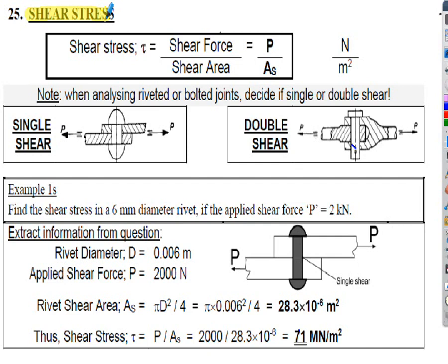Now these calculations are very similar to what you've already done with direct stresses, because if you remember, with direct stresses we had a formula. I'm using symbols here, but the stress, sigma, was given as the force in the member divided by the cross-sectional area. We were talking in those cases of pieces of bar, for example, with a load P applied, and a cross-sectional area through there, circular section maybe, and the stress in the bar was the force applied divided by the cross-sectional area.